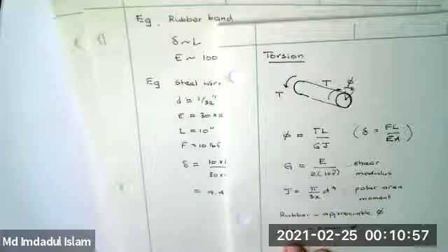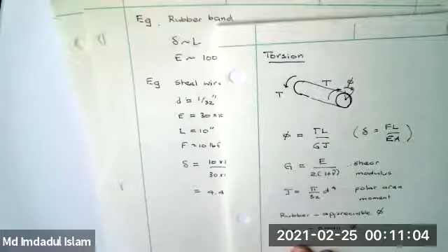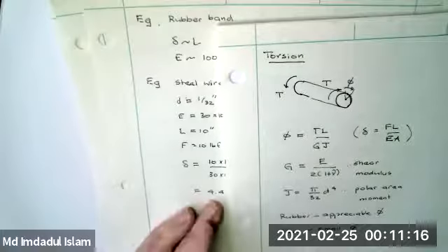I started off this introduction by saying sometimes deflection criteria. Deflections are usually so small in steel and aluminum products that deflection is negligible. You don't really have a design criterion for it. You don't need to worry about it. It hardly moves. That said, we still need it for statically indeterminate metal structures.